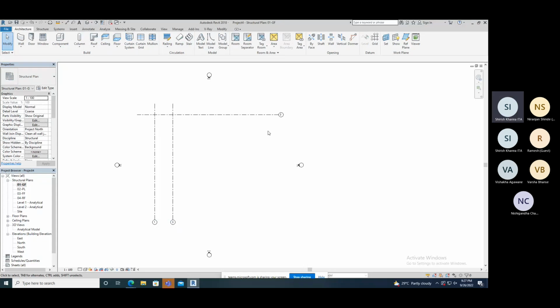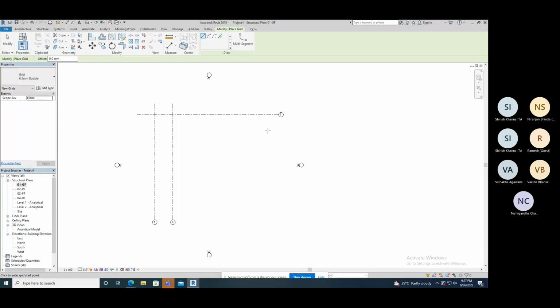Otherwise we have offset option also. Now see, in grid GR, you can use the fourth option, pick lines. Whenever you are clicking in it, this small toolbar is known as option bar. In this, we have option to click offset. I'm giving here 5,000 value and enter. Then only you need to select like in AutoCAD. See, select on this side, so you can get this side offset.